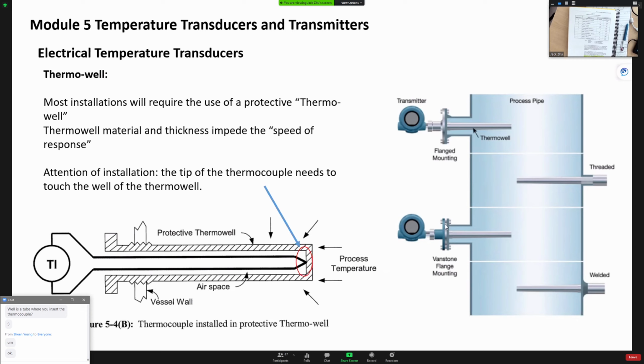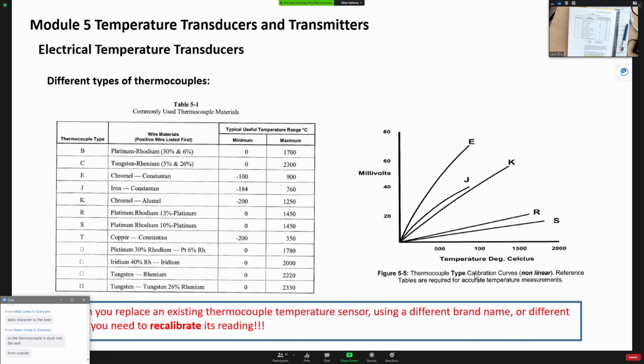Yes, okay, yeah. Because you try to measure the temperature here. Let's say if here is milk or beer, your thermocouple is industrial equipment. Do you really want to put that industrial equipment into your drinking water or drinking beer? No, right? You want to have some kind of food grade thermal well built in there, so you're not touching the beer or milk. You insert it in there, you mount it in there. If you want to replace them, you can just take it out.